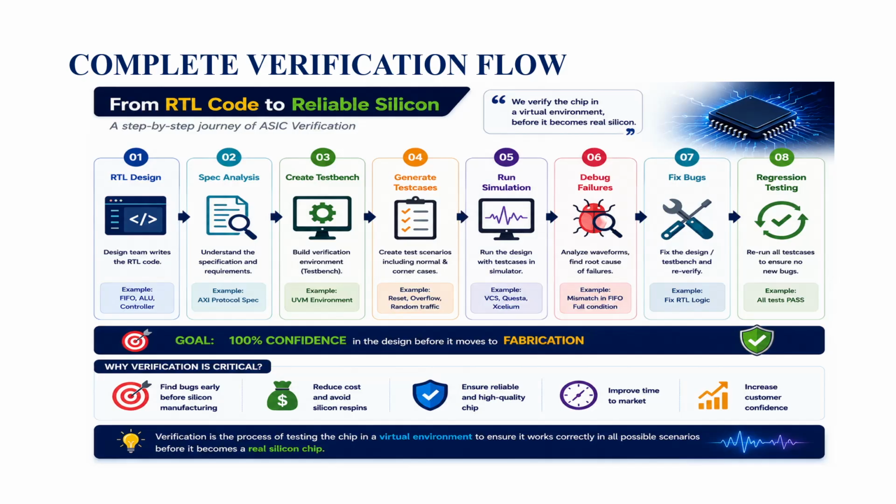Once we have completed running the individual test cases, now we go to regression testing. What is meant by regression? Regression means I am checking my RTL with the help of multiple test cases, running multiple scenarios together. That is what we call regression testing.